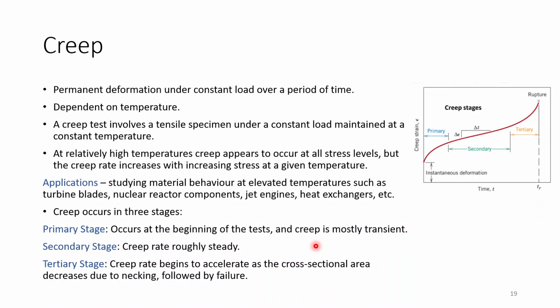At relatively high temperatures, creep appears to occur at all stress levels, but the creep rate increases with increasing stress at a given temperature. The applications are in studying the material behavior at elevated temperatures, such as turbine blades, nuclear reactor components, jet engines, heat exchangers, etc.